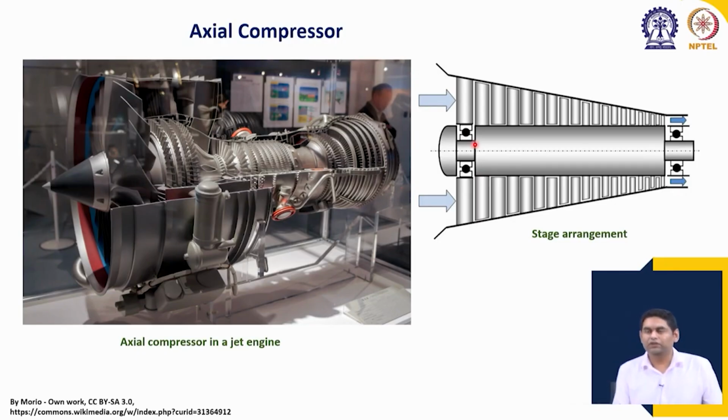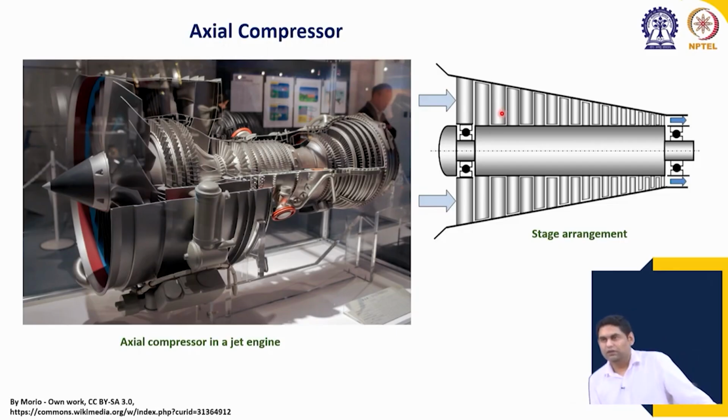So, unlike a motor which is used for, say, fans, in this case the compressor is directly driven by the turbine. Okay. It is a direct connection, direct drive to the turbine, no gears or other mechanisms are used. So, almost the entire power can be transmitted to the compressor. Again there are fixed blades for guiding the flow and converting the kinetic energy into enthalpy, and this process goes on until the flow goes out axially. The size of the blades keeps on reducing.